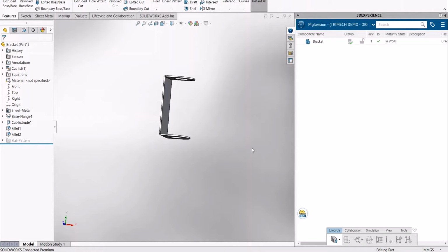What's very important is that when we're finished making changes, we need to turn off the working under change icon. Otherwise, any other items completely unrelated that we might open would accidentally get added to the change action under its scope as well. So we've got to be careful to turn it on, but just as careful to turn it off when we're finished as well.